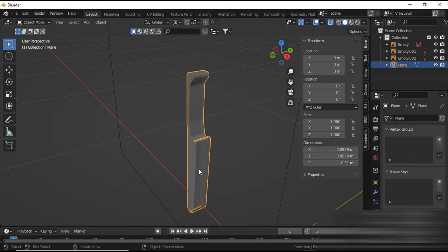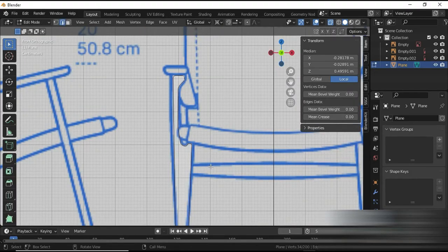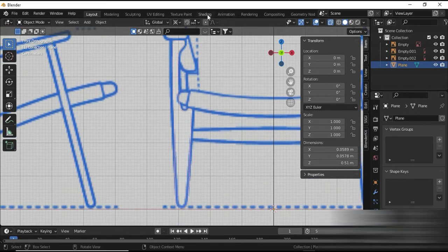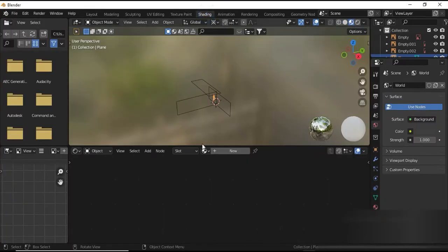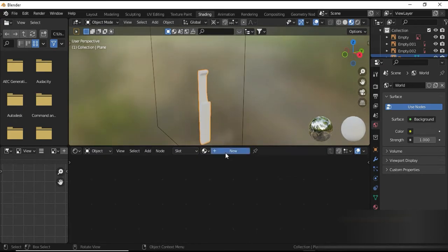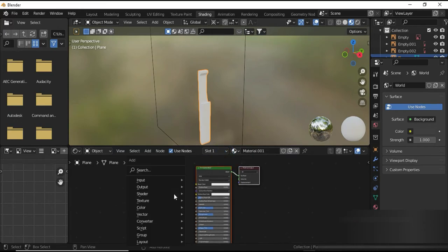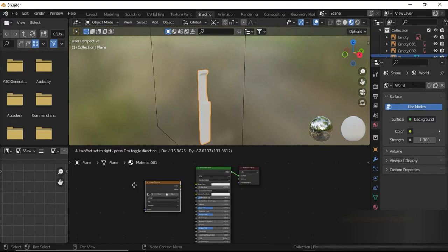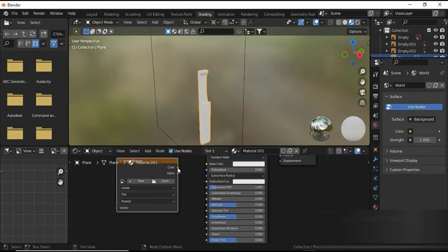That was fun. Now how do we fix? Our scale is the same, our intuitions, right? So guys, we're done. So now, another very important thing is your UVs. Make sure that you fix your UVs along the array, because later on you'd have to do it anyway. So why not, let's do it right now. And there's a shortcut for fixing your UVs, and it is temporarily installing a UV grid on your element. And when you fix that UV grid, and then later on when you apply your image texture or your material, it's going to be applied properly.